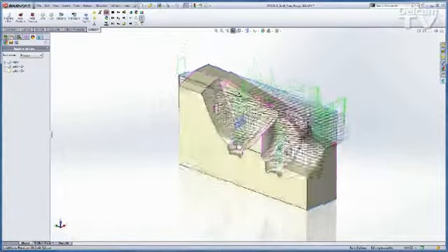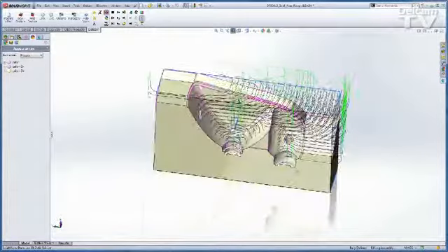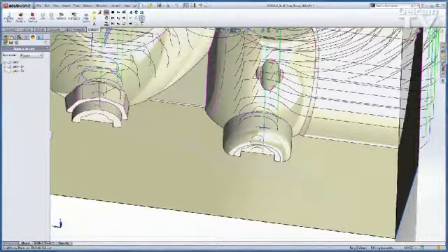And if you look at this tool path, it's going down into these small pocketed areas. And this area is so small that the tool is never really moving completely off of this center material. So that center material is building up and building pressure as the tool moves down. And it's going to at least damage the tool, if not break it, or at least the inserts. So what we want to do is have a nice way of eliminating these areas.